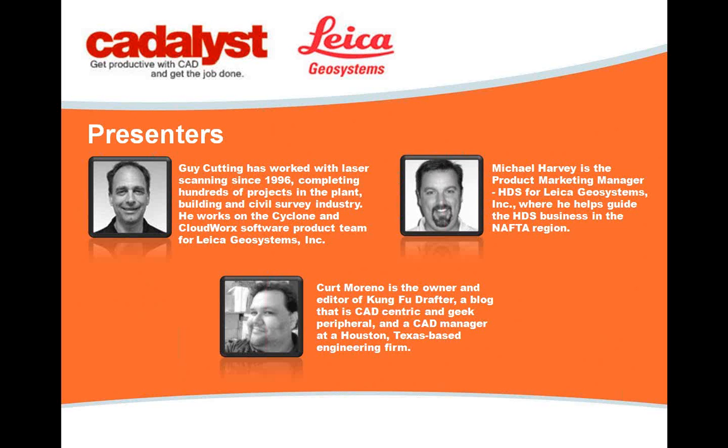However, if there's very shallow standing water, chances are that the laser will penetrate it. By shallow, I mean probably less than an inch, probably closer to half an inch or less, and it'll penetrate that. I'm lucky enough to have a pool in my backyard, and I've actually scanned the pool, and the walls of the pool go off at a crazy angle just because of the refraction of the light through the water. Well, we definitely don't want any crazy pool walls.